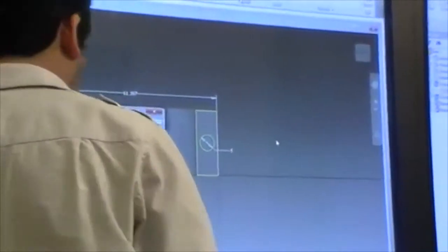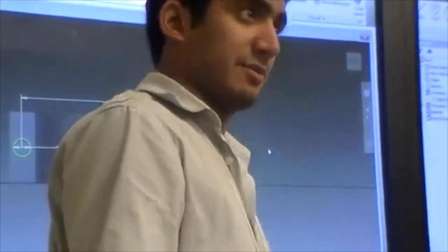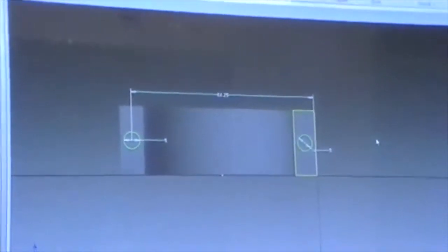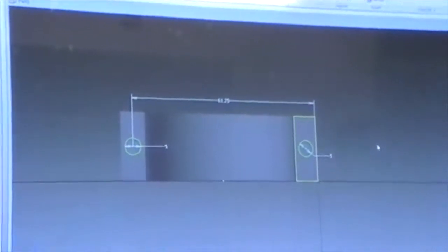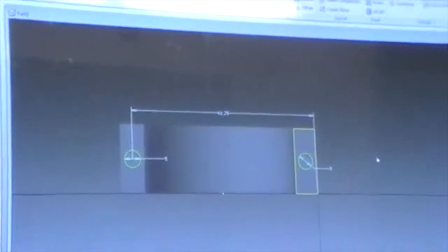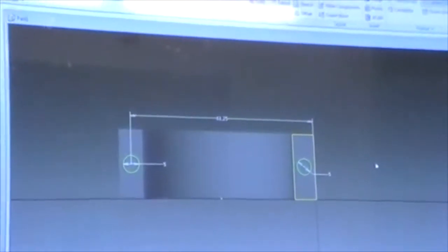Right, okay. So the center of 7.5 is what? 3.75? Is that it? Yeah. Okay, so 3.75. So I'm going to knock off 3.75 from 65. So you have to do a little bit of mental math here. So that gives me 61.25, right? So 61.25. Sure. And now you've got, okay, this is now properly constrained. It's at the center of that rectangle, and it's got a good geometry, right?